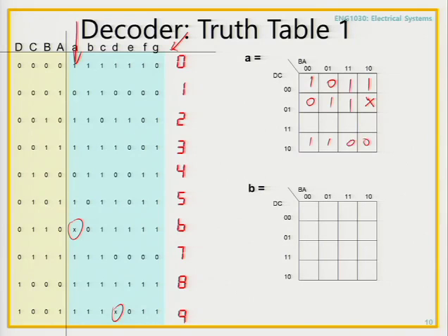Actually, what could I put in here when the output goes out of range? So, sorry, when my input gets bigger than 9, I can put a whole load of don't cares in here, yeah?